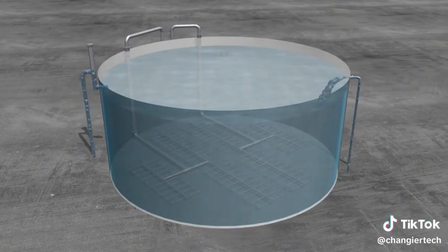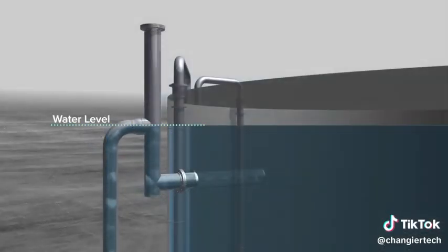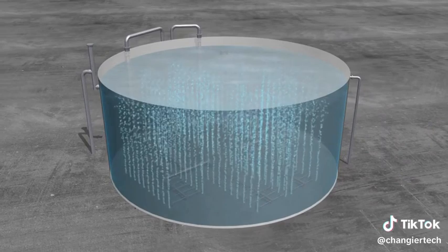The MBBR process is a 100% flow-through process, meaning the flow rate of the reactor effluent is the same as the influent coming into the reactor. In industrial applications, the water level, or side water depth, is maintained by the gooseneck effluent piping on the outside of the tank. This allows for the reactor to reach its maximum retention time and for complete submergence of the media retention screen. The inside of a reactor does not have moving parts that will require maintenance.